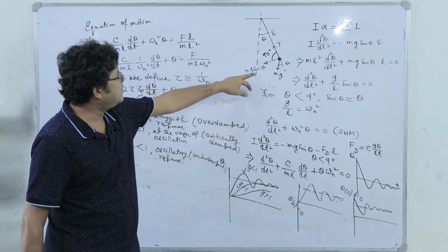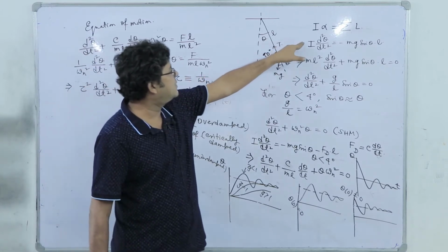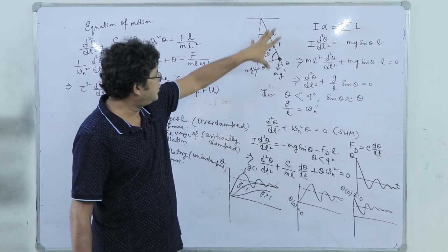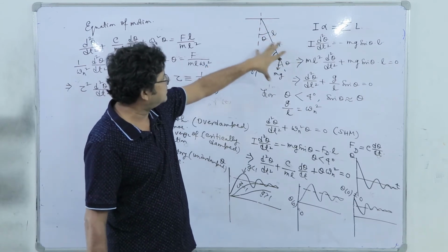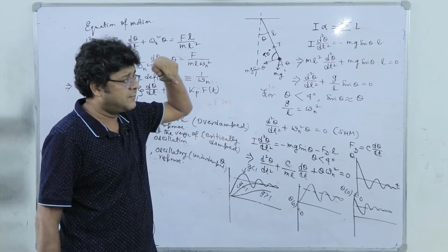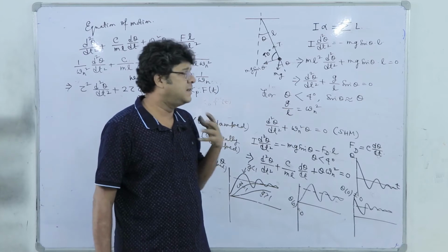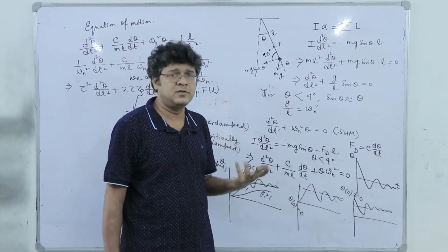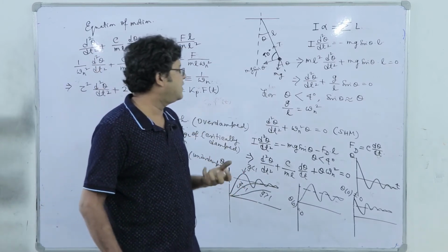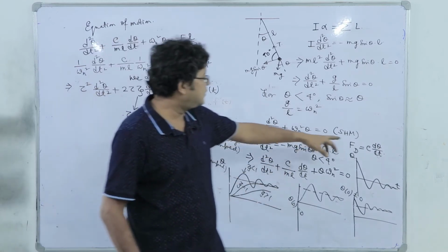So the pendulum initially is at a neutral position, and now I am giving a force. It may attain a definite specific location, dictated by what sort of fluid it is suspended in. If it is a lube oil, it will give you a high resistance. So with the same force, it will very slowly and sluggishly attain this equilibrium value of theta. With lube oil the response is overdamped. If it is water, it has less viscous resistance.